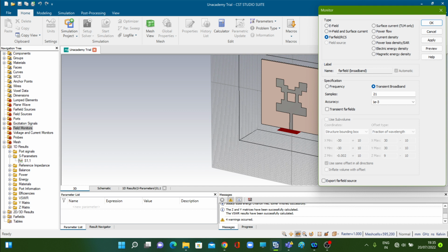So again here, there is some optimization which is necessary. We need to decide whether we can afford some more time for the simulation results to come, or we need to get the simulation results in a very short time, whatever be the quality. That optimization we need to do. So let us take somewhere in between. Let us change this to 30, for example.